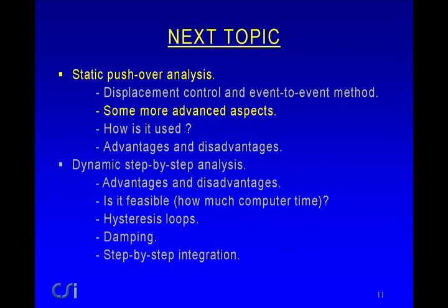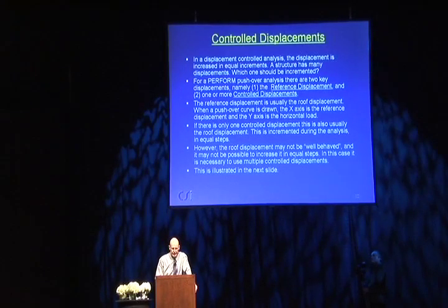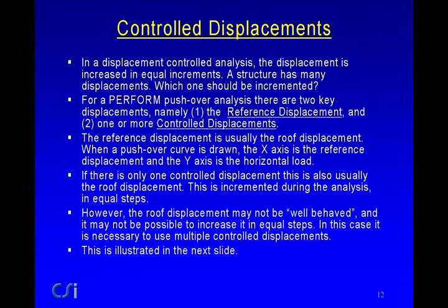So the next topic, that was just very briefly on the basic method. A few more advanced aspects. This is something that you do need to consider, and this is controlled displacements. And as I showed, in a displacement-controlled analysis, you increase the displacement in equal increments. And the thing is, the structure has got lots of different displacements, thousands of different displacements. So which one do you want to increment? You can choose any one of those 1,000.